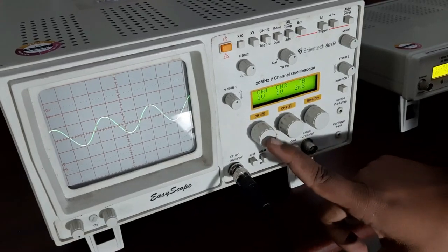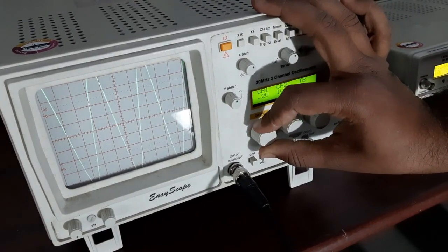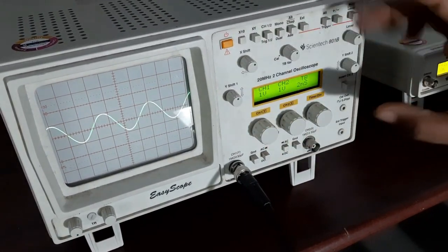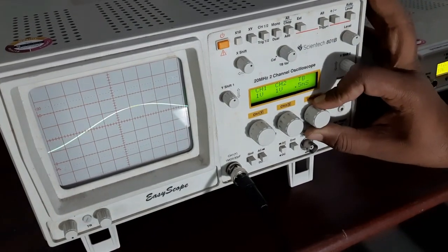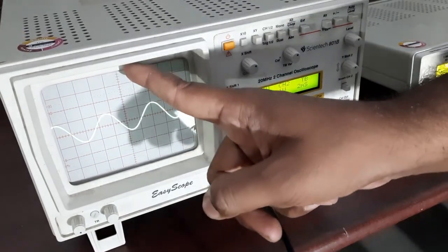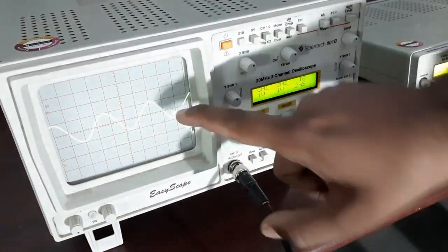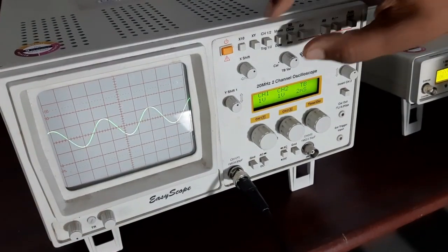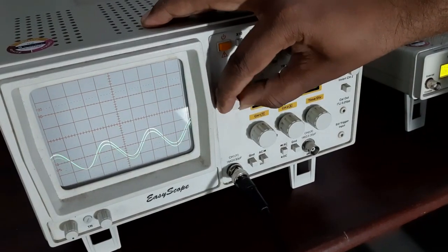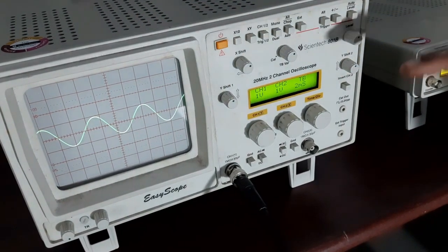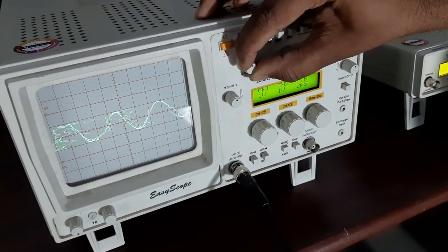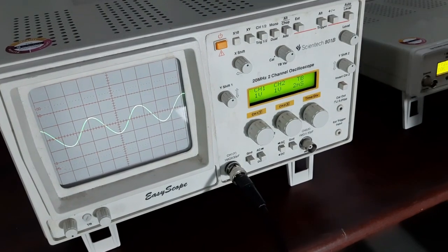We can change the x-axis and y-axis division. You can see I am changing the channel per division, which is changing the y-axis division, and we can also change the x-axis division using the time per division setting. Remember that we are not changing the amplitude and frequency of the wave, we are just changing the y-axis and x-axis division on the display device. In this CRO we also have an option to shift the waveform up and down using the Y shift, and to shift it left and right using the X shift. According to your need, you can shift it wherever you want using the CRO's display options.